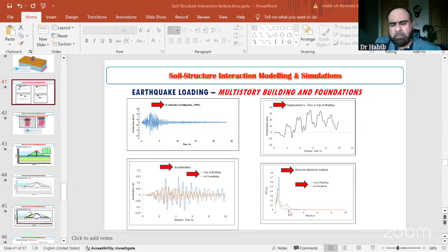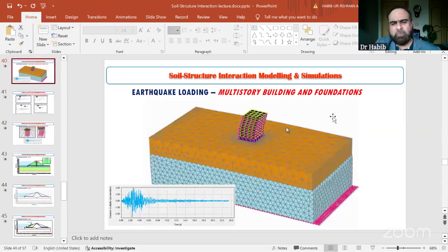So that's why, for realistic modeling, generally I agree with him, but for specific modeling, we will get the right spectral accelerations against different periods, and then we can compare these with our structures. But in any such modeling like this one, in this slide, we are already shaking our structure in a natural manner. So if there is a problem from the specific period wave, definitely the structure will show it, in the form of very high stresses or deflections in the structure.